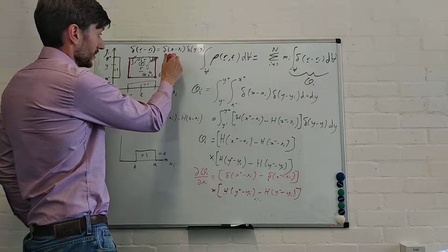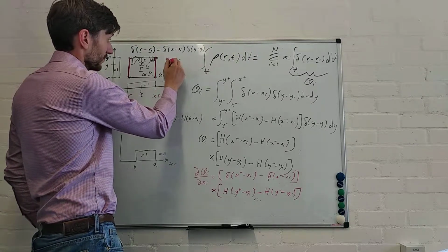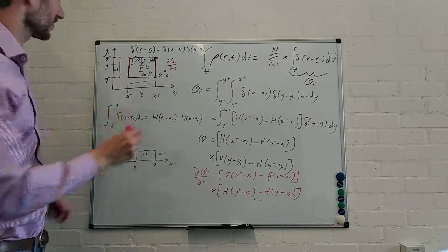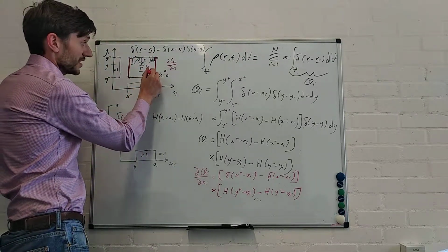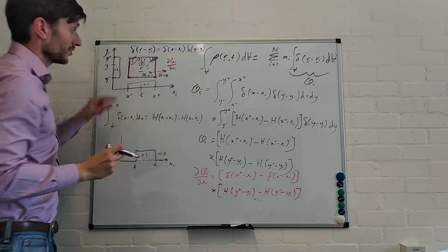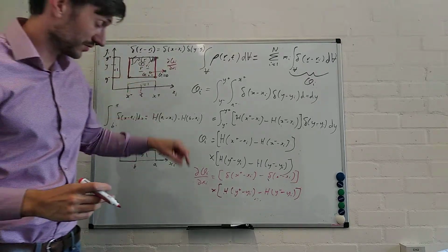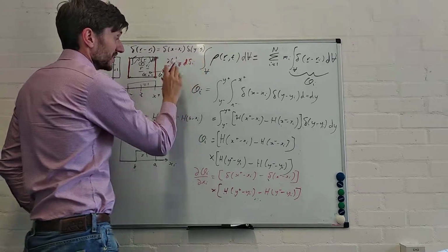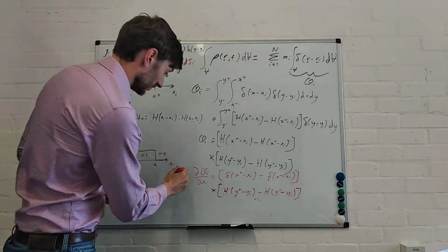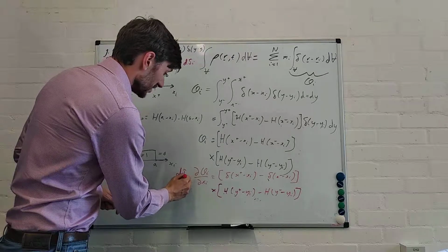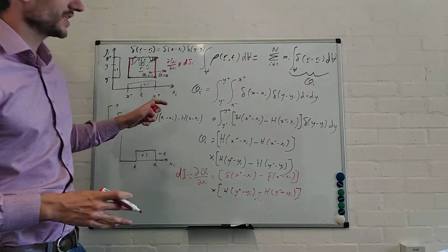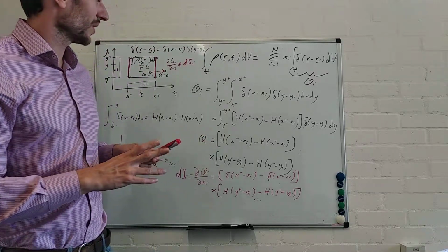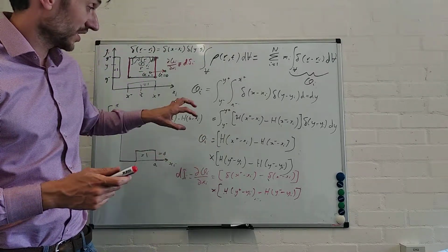Exactly. So d theta i by d xi is an expression that's counting only the surface crossing. What that means is we have an expression here that only counts molecules as they move across the surface. So we give this notation dSi, essentially the equivalent of the continuum surface flux. So between these two pieces we have all the ingredients to express the molecular version of the continuum control volume equations. That is surface fluxes and values inside the volume.